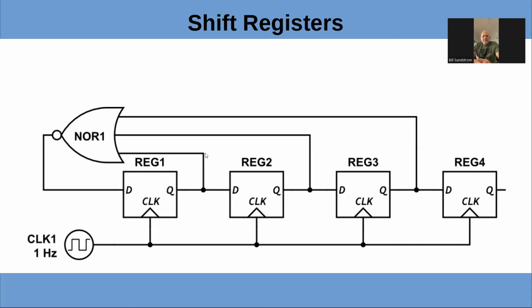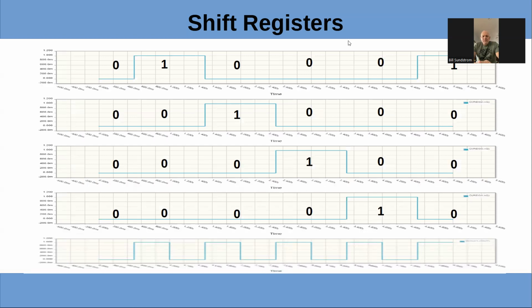The Q changes, but it's still going to be a 1 on the input. It's going to stay 1. Any one will give you a 0 at the D. Yes, you're right. So we're just going to shift a single pulse through, which is probably on the next slide. Probably helps if I reviewed these before. There it is.